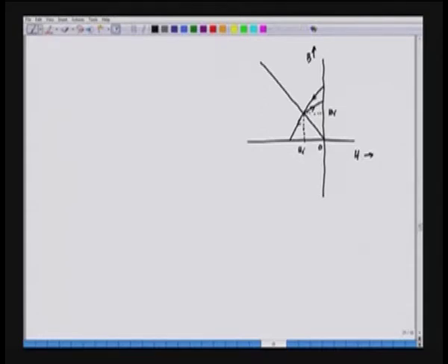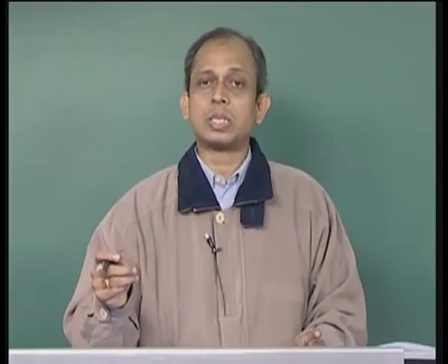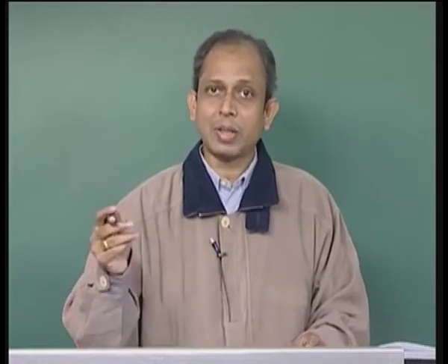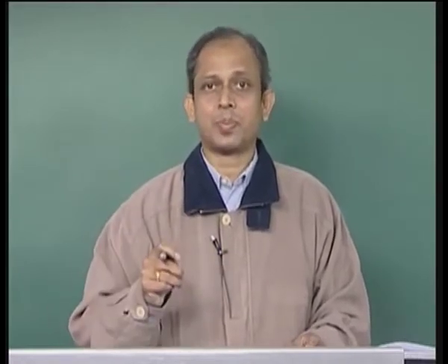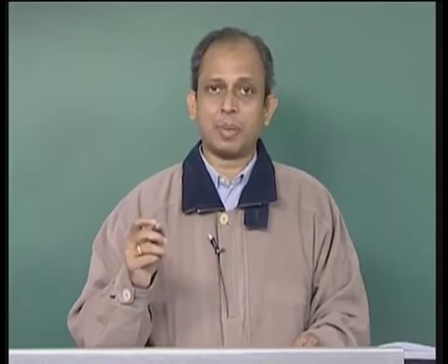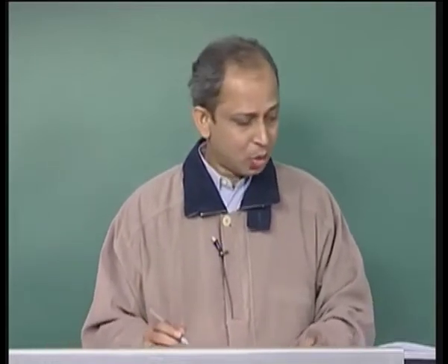Now, this line after something, if you again decrease this, it will come back here, and after a few cycles this line will be stabilized, and this line is called the recoil line. So, this recoil line is the line in which the characteristics move, which is different from the original BH curve. This is the original BH curve, and the recoil line is the line in which the characteristic actually moves when we increase or decrease the current. It departs from the original BH curve. So, with this background, let us go forward.